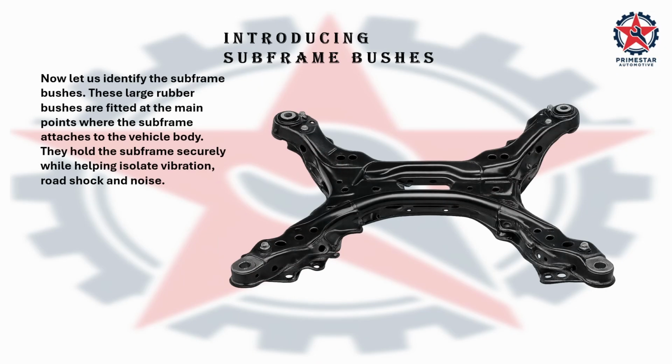And let us identify the subframe bushes. These large rubber bushes are fitted at the main points where the subframe attaches to the vehicle body. They hold the subframe securely while helping isolate vibration, road shock, and noise.